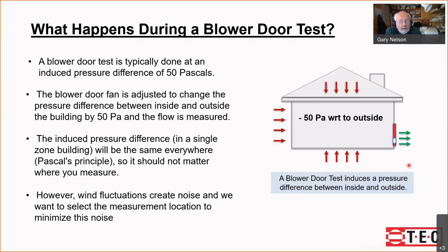Physics says that if the interior of the building is one zone, in other words, there are no pressure differences across floors or walls, that change in pressure difference will be exactly the same at every location where you would measure the pressure difference between inside and outside.